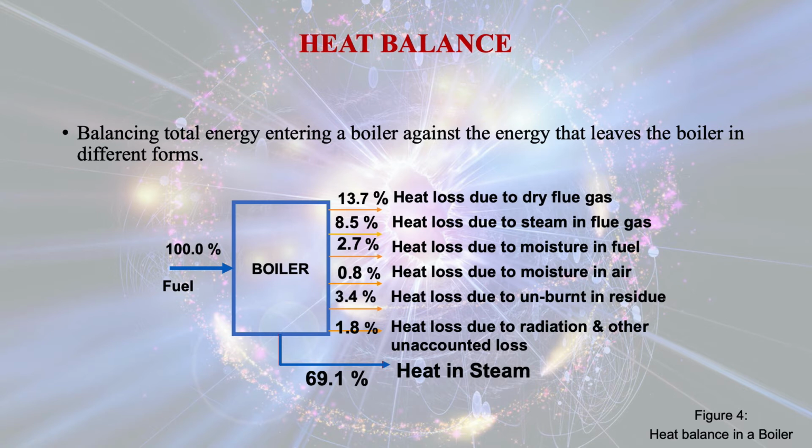For this case, around 13.7% is heat loss due to the dry flue gas. 8.6% is heat loss due to steam in flue gas. 2.7% is heat loss due to moisture in fuel. 0.8% is heat loss due to the moisture in air. 3.4% is heat loss due to unburnt in residue, and 1.8% is due to heat loss, radiations and other unaccounted losses.